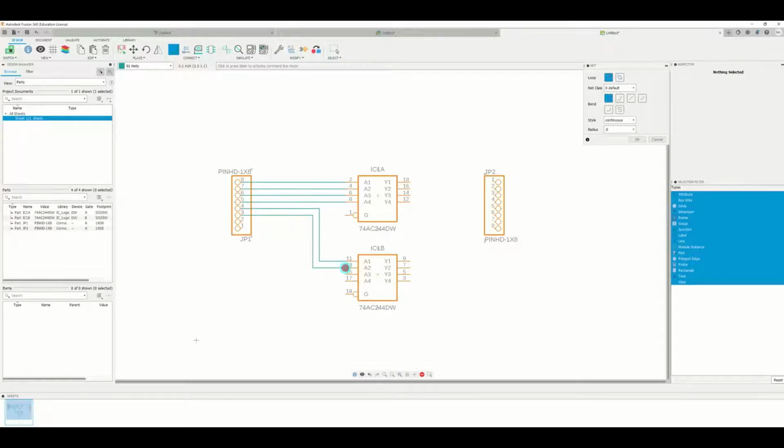You have to take care of this such that you align the wires. Of course, later you can move them like that. But yeah, it's by trial and error. Then you can select. Later you can turn on the grid, so you would see where your lines are. Okay, like that. Now, if you make a mistake, you can always delete. If that's okay, then you press cancel. Okay, so now you have a line connecting the pin header JP1 with the inputs of the 244.